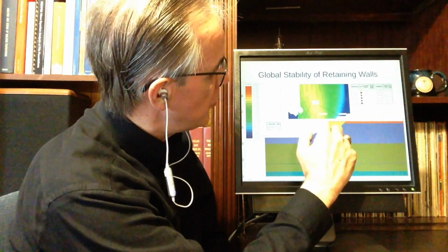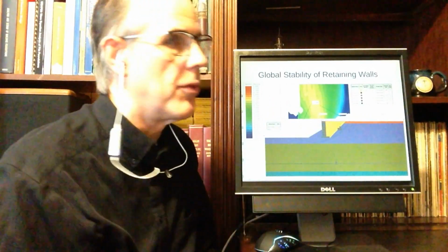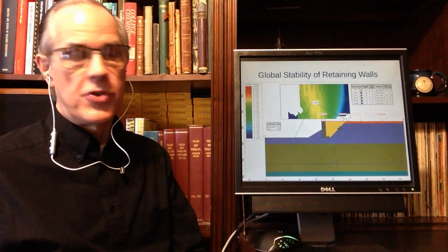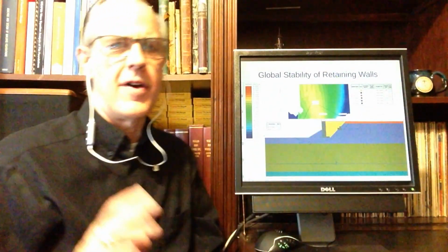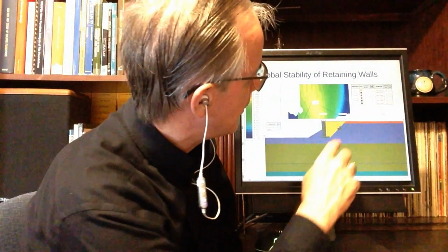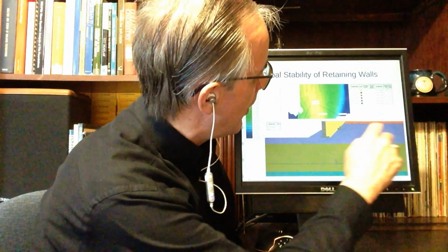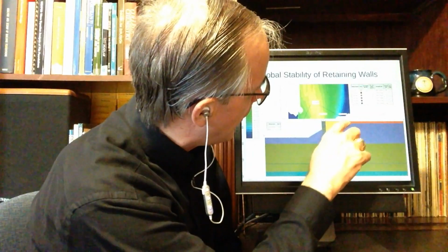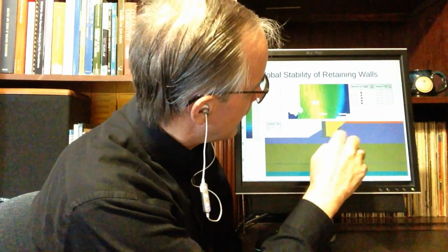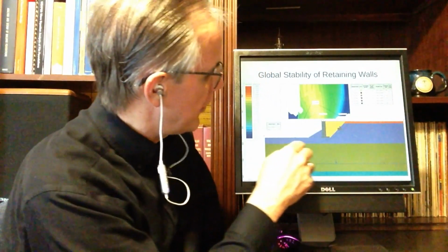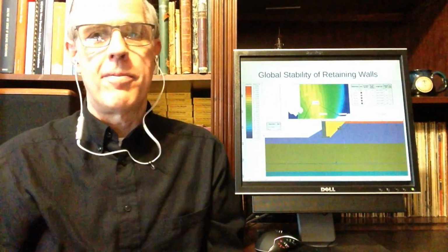It also includes the loads on top of the wall, because the wall is additionally, in this case, being used for an abutment. So you've got vertical loads from up here. We're going to avoid that particular issue at this point. It also has loads for surcharge loads along the wall. It also shows you where the failure surface is for the wall itself. It shows you how they've put a little thing in here to break that failure surface. And so we also analyze for global stability. This is probably the best way we have for analyzing for global stability.